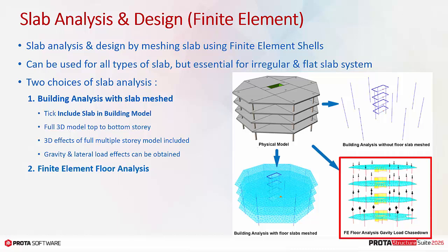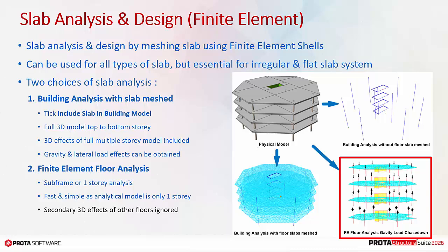The other option is finite element floor analysis. The analysis considers a subframe of one story only. It is fast and simple as analytical model is only one story. Secondary 3D effects of other floors are ignored. Only gravity load can be obtained, that is, no lateral load analysis.